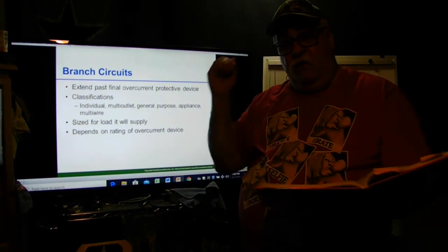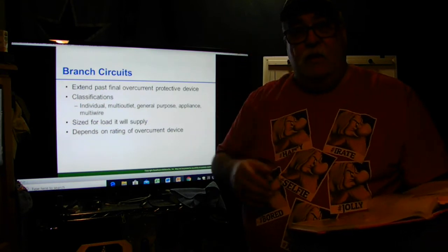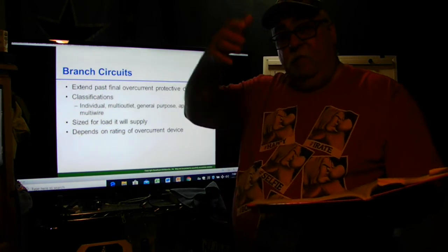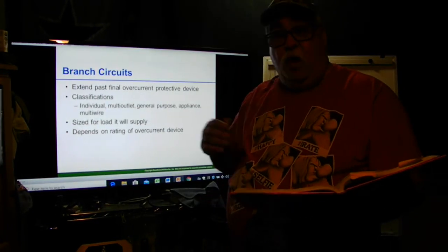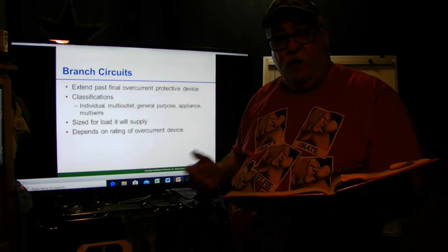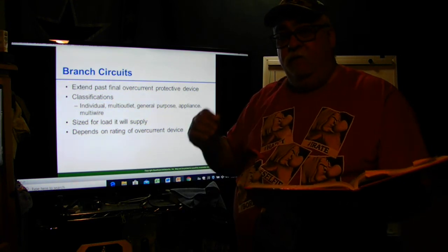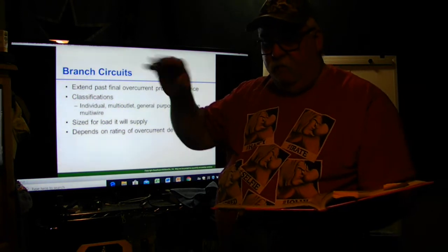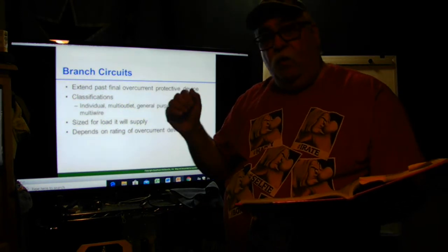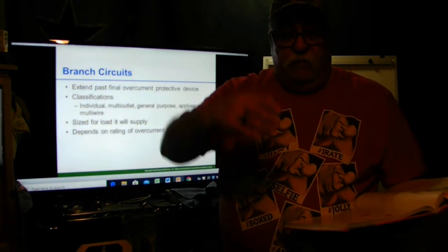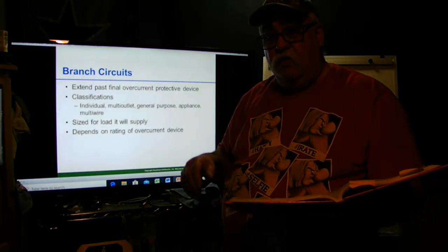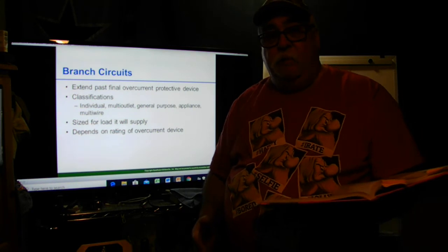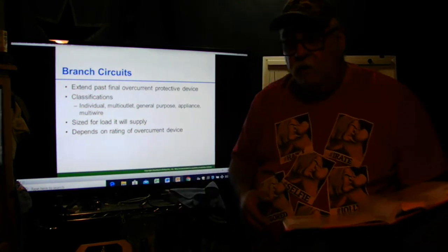If we got a feeder that's feeding the panel, that's feeding the bank, that's completely different, because we're coming off a breaker to feed a bank of fluorescents off of a sub panel. I've done it many times when we come in and we have a 50 amp 3-pole breaker feeding fluorescents in the room, and then it goes down to a time clock that turns the power on and off. It's got a little sub panel there, but it's considered a feeder.